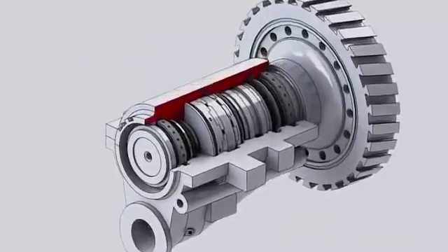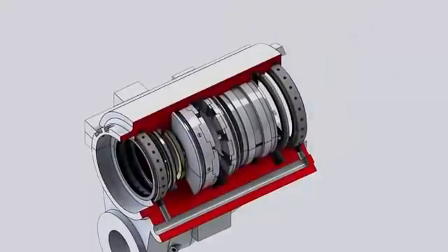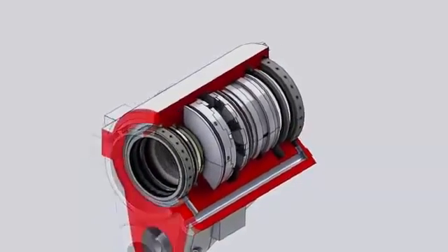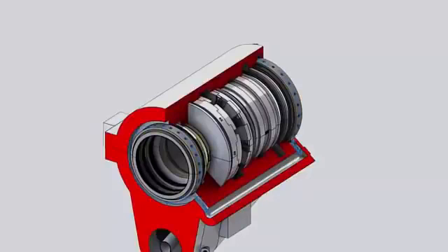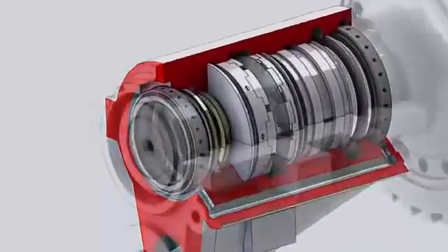The sealing airflow from the cooling and sealing system goes through the axial tube machined at the right side of the housing and is admitted to the labyrinth seals through 2 ports to annular spaces surrounding the seals. Between the 2 rows of seal teeth, sealing air is admitted through multiple radial holes to stop oil from spreading along the shaft. Some of this air returns with the lube oil and is vented through the lube oil mist eliminator, and some escapes out of the housing.